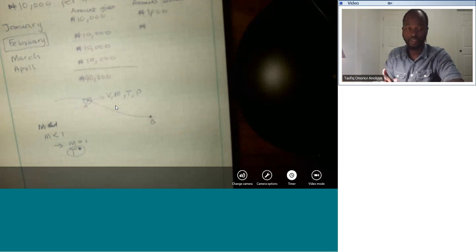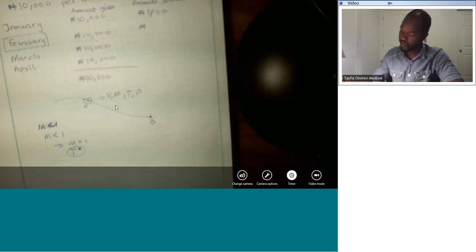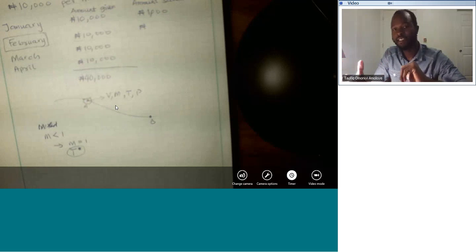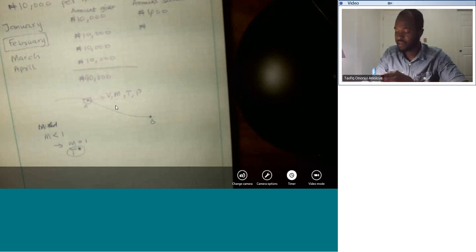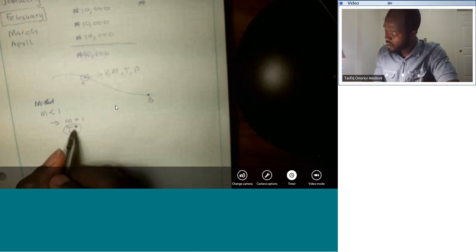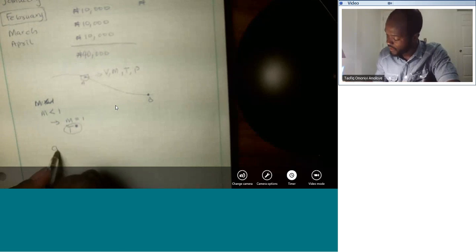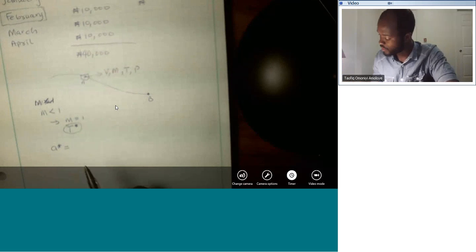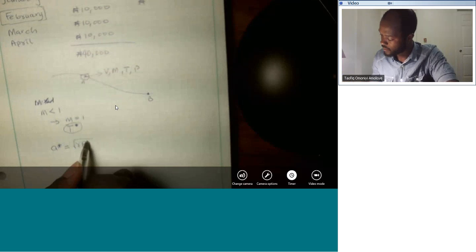If it's going to be speeding up, it's most likely going to be speeding up in a non-adiabatic process. Well, now in our imagination, we are assuming that it is doing that adiabatically. That means all the energy that it possesses is not allowed to exchange with the surroundings. So the fluid element is allowed to keep all its energy as it's being sped up or slowed down. So the temperature it has at that imaginary state is T star. Immediately that we define T star, we can also define a speed of sound associated with that imaginary state, and it's just going to be equal to the square root of gamma R T star.